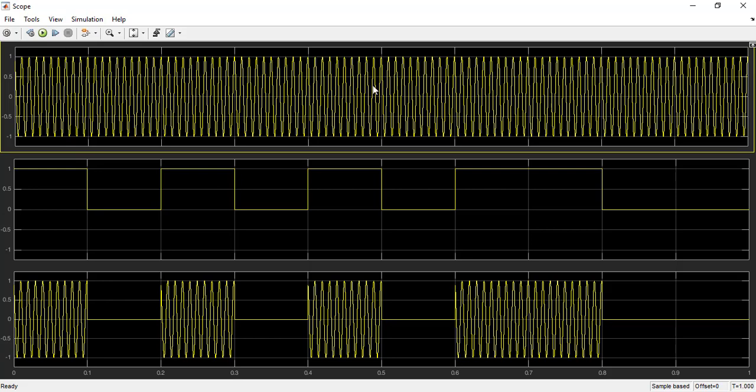First one is our cos carrier. The second one is basically the digital sequence 10 10 10 10 10 10 10 1100. The both are multiplied, and then there is our on-off keying output signal. So the modulation is done.